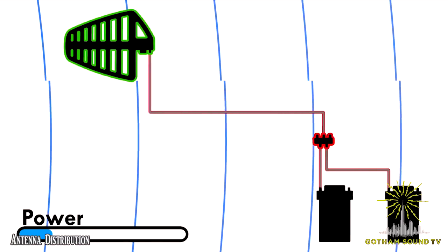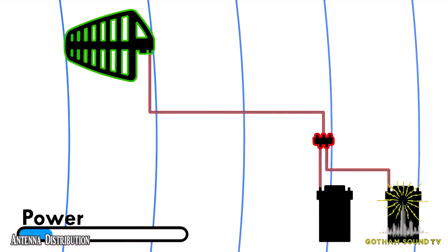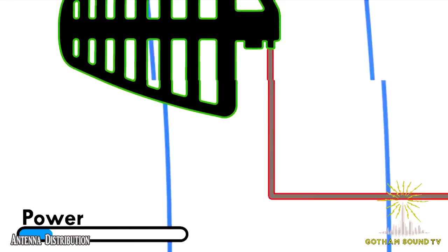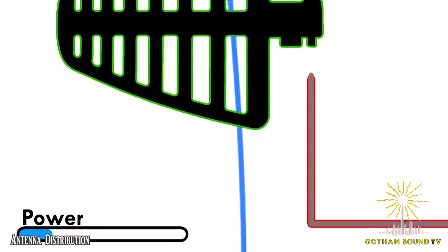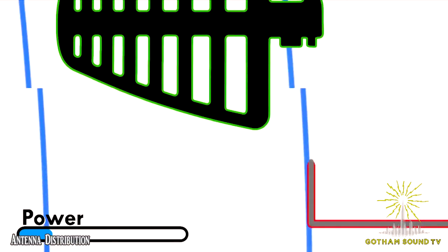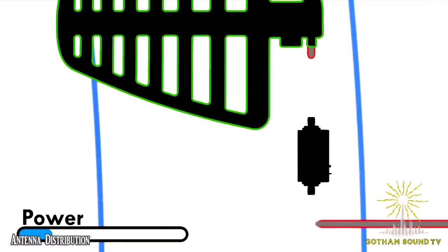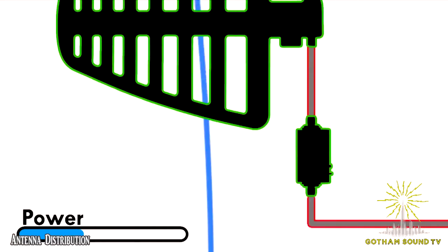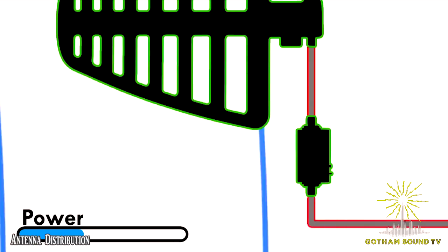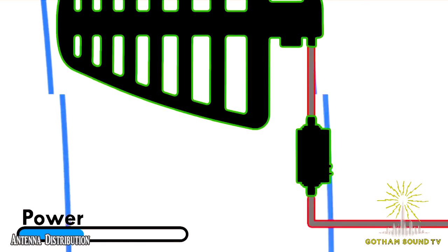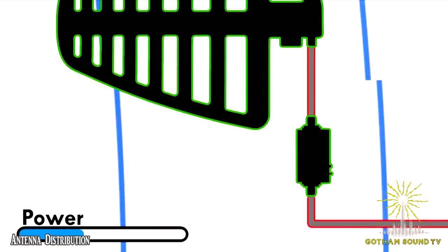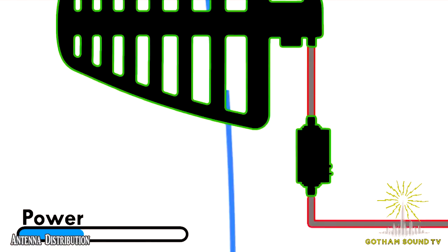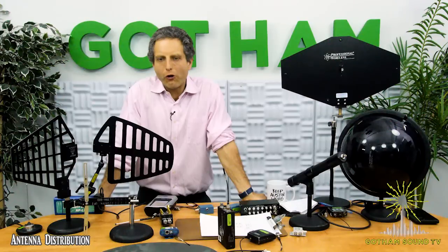So how do we do this? We come up with an amplifier, and in our amplifier, we're going to put it in the first place that we can make up the loss of signal between the cable and the antenna. And we want to set that amplifier not for its maximum setting, but for just enough to overcome the losses of the cable and the splitter. And that's really the key to this, is where we don't want too much gain.